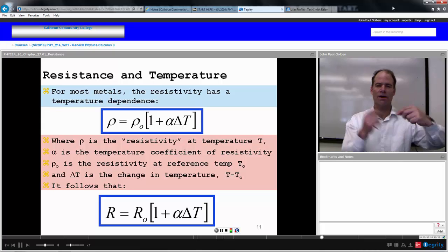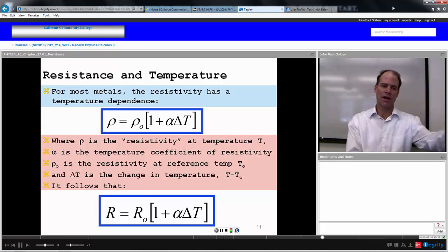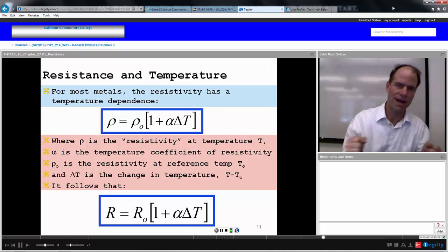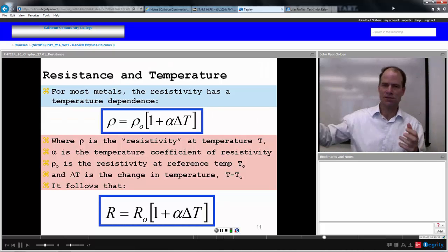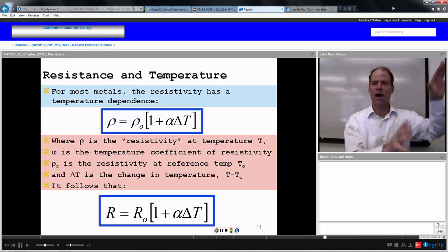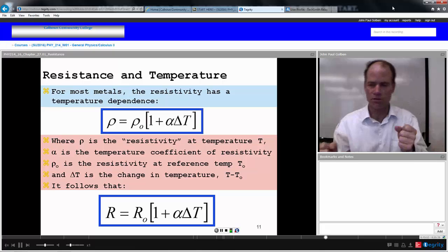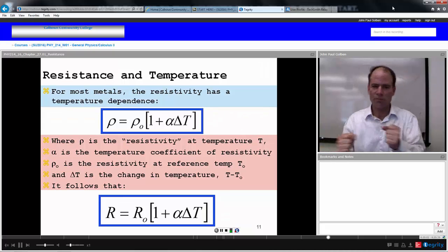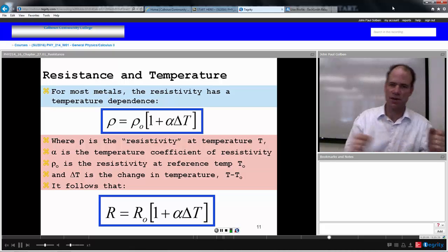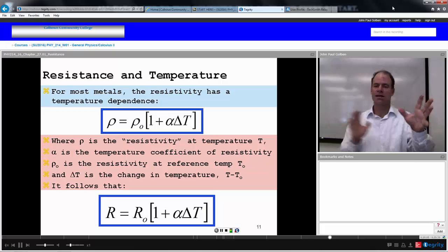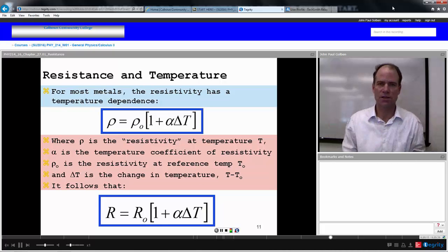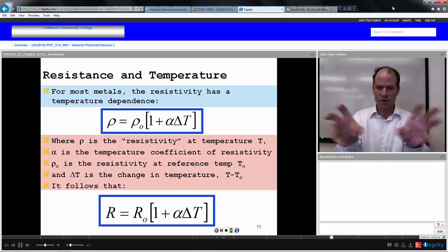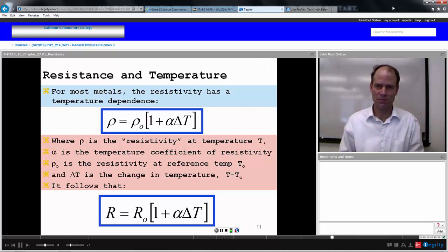Say I had a wire, and you are an electron trying to get through the wire, and you're encountering problems. There's other electrons who are resisting you, and there's positive ions that are attracting you, and you're being pulled all over the place. If the temperature goes up, all these other guys are moving more. The atoms are moving around more because of the temperature, and so are the other electrons. They're moving and shaking around more. So if you're trying to get through, it's going to be harder when these other components are moving around more because of the temperature. Hence, you're going to encounter more resistance.